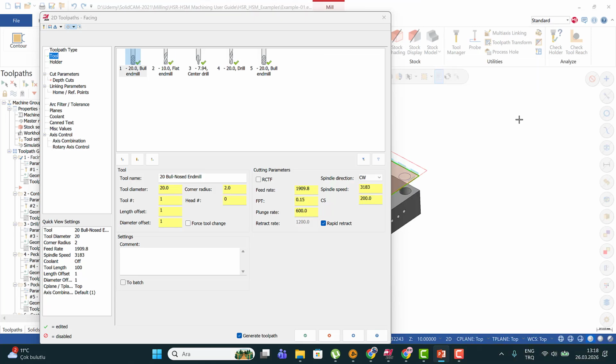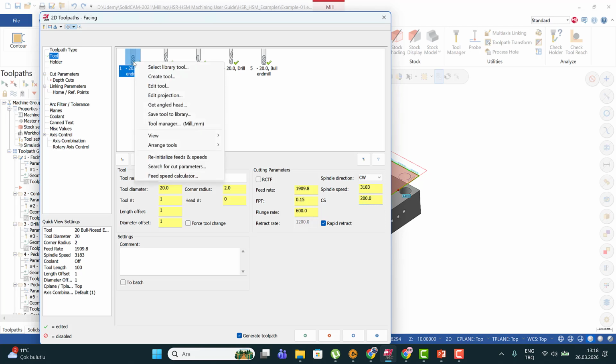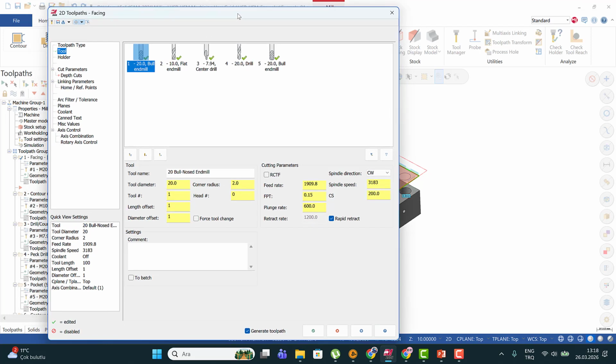But in Mastercam, we don't need to focus on that kind of formula. We just need to come here to organize our cutting speed. Of course, we also need to think about which tool diameter we should use in our milling operation, for example a 20 millimeter tool or a 10 millimeter tool. That is also a quite important question we should ask. This is my cutting speed parameter, and according to it we can easily calculate our spindle speed. Our spindle speed unit is revolutions per minute.